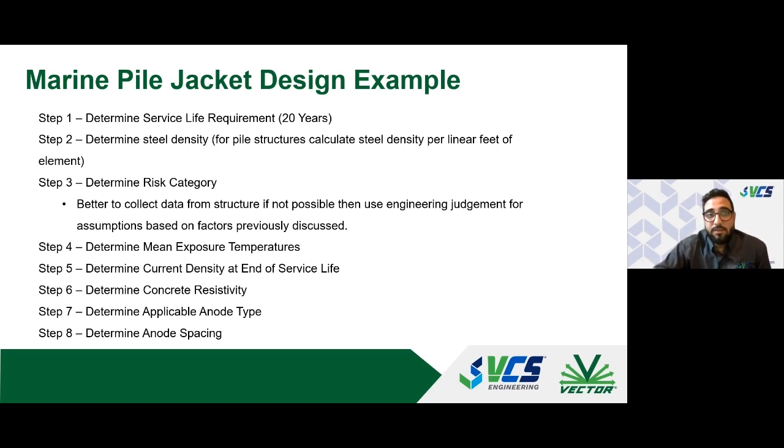Step two is really calculating our steel density to see how much steel we're trying to protect and how much steel we're dealing with. For column structures or piles, usually steel density is calculated per linear foot of that element.